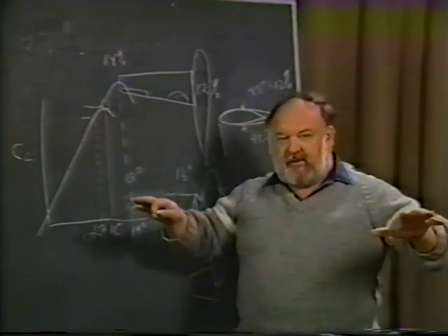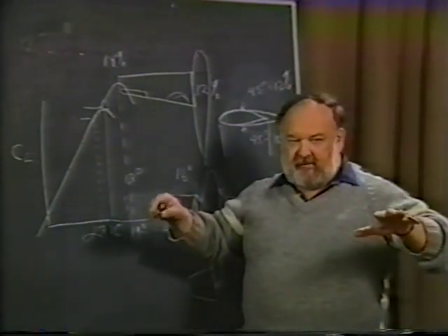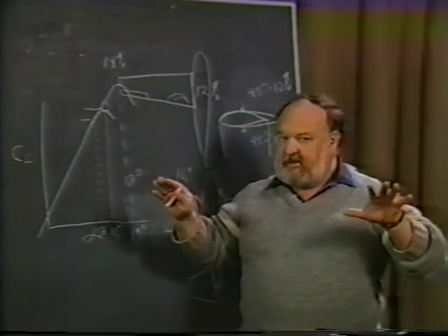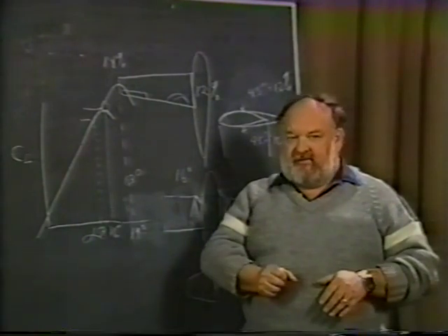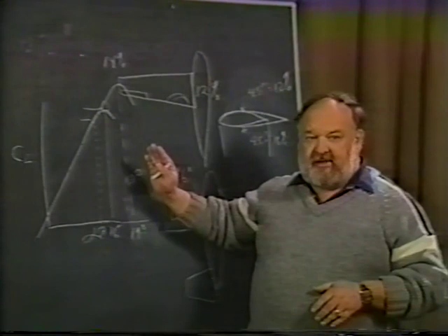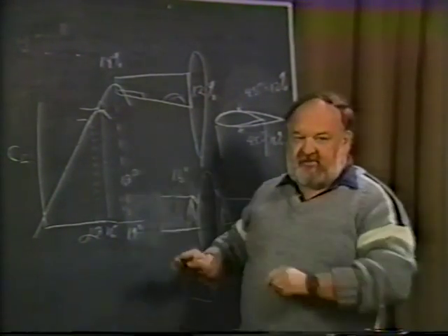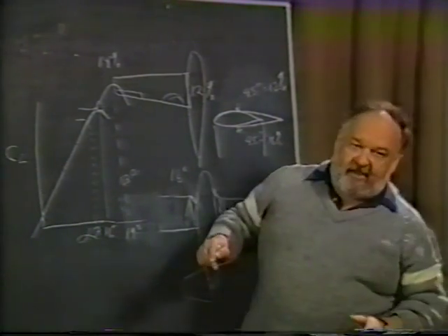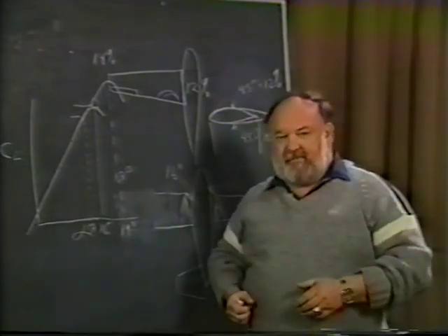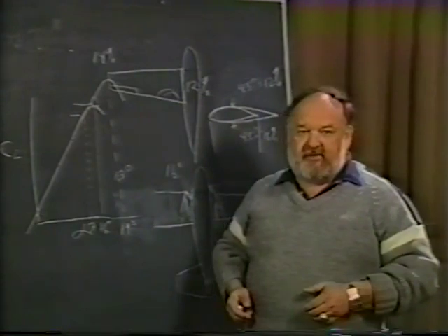Here you are with the straight wing, straight sections, the old USA 35B airfoil on it, and it'd be real fine, except if you were near a stall, you still hadn't stalled yet, the airplane's flying, and then you go ahead and move the stick to the left, and the right aileron comes down. As it comes down, it tries to produce more lift out of that wing than it's capable of, and that section stalls. Now what did happen? You wanted to bank to the left, so you gave left stick, but now the right wing stalls and the airplane goes the opposite direction. Immediately it confuses the pilot, and off you go, possibly into a spin.